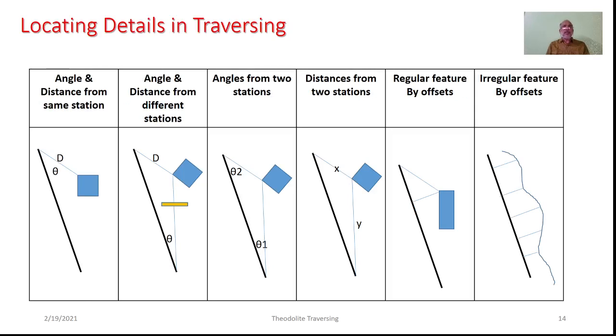So all the methods that we discussed, maybe loose needle, fast needle, are essentially for the continuation, or to have the travel along the series of survey lines. Here, as we are more interested in locating the details, we have to take a reference of all that are the survey lines. So here again we will be making use of the second principle of survey.